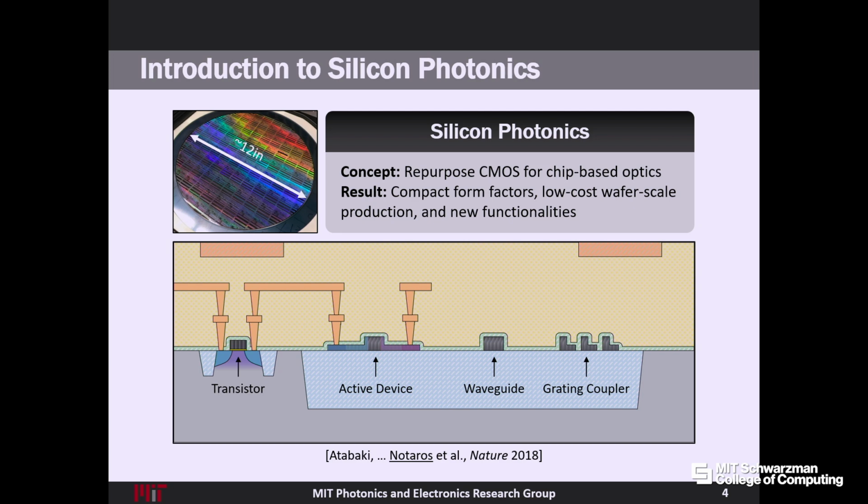So what we would do is we could maybe take this waveguide and create an active electro-optical modulator. You'd have your waveguide here that's confining and guiding your light, and then you extend it on either side. And then on either side there, maybe we'd put some of those dopants in that allow us to have electrical properties in this silicon. And we place metal down into contact with those dopants. And now we can apply a voltage across that waveguide.